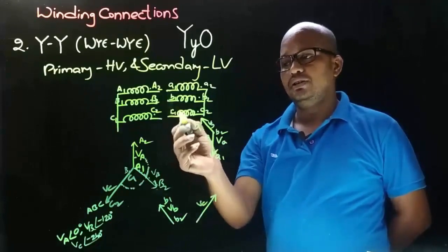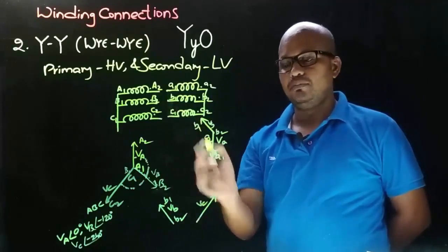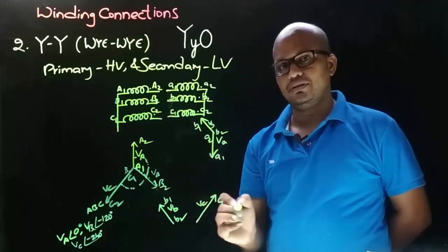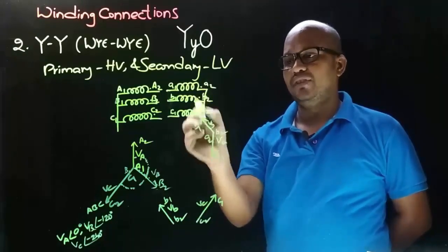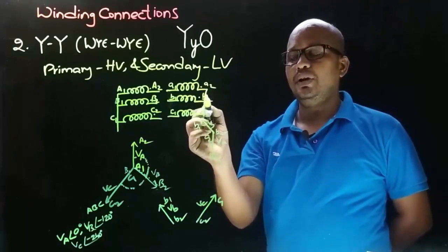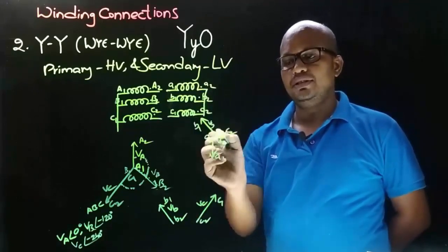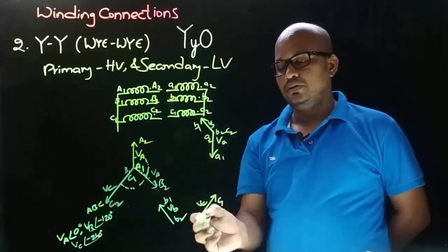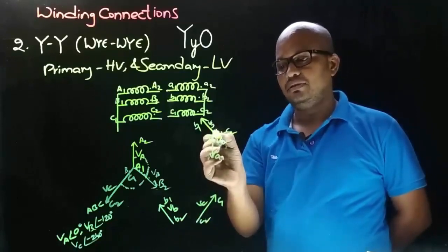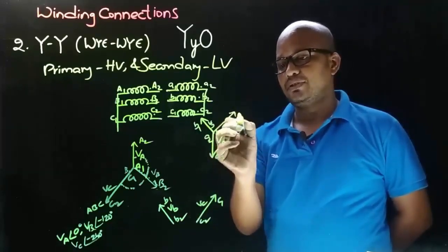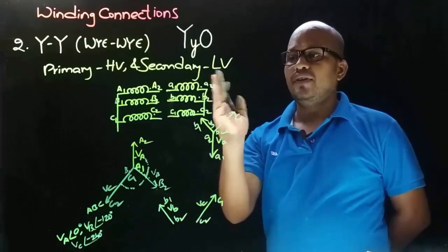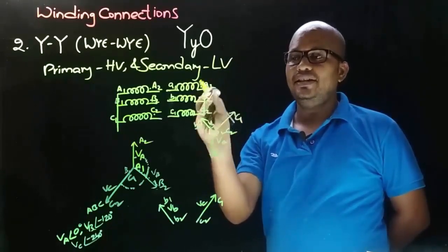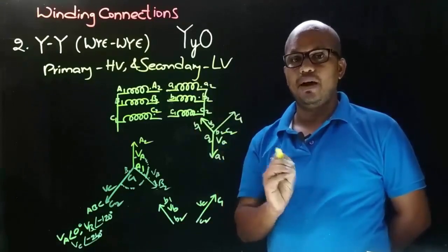Here the output is taken from non-dot end, means arrow points towards C1 and this will be C2. And now observe that in the winding connection, to A2 and B2, C2 is connected, means here C2 will be here. So draw this phasor like this. So this will be C1. So this is how the phasor diagram for the secondary side star connected winding is obtained.